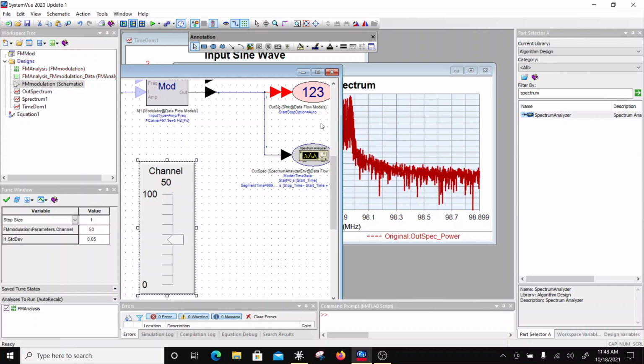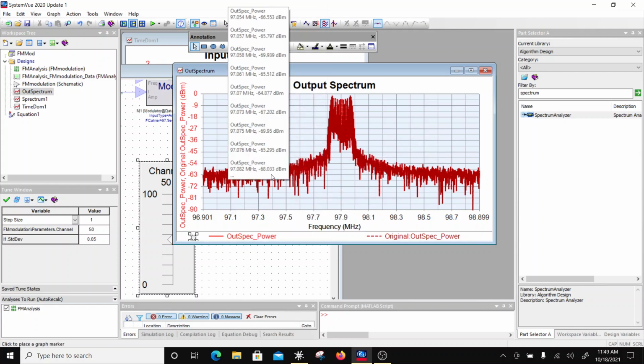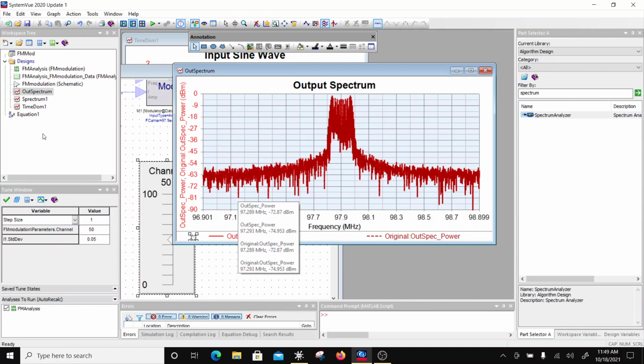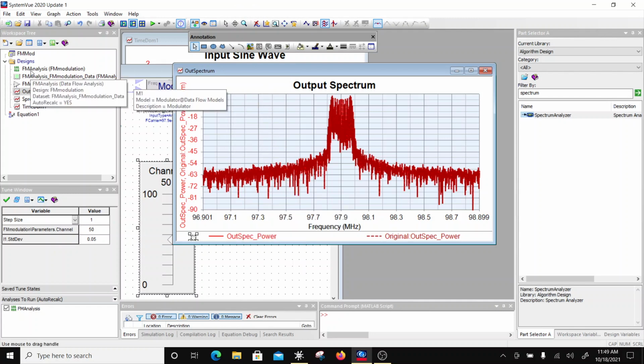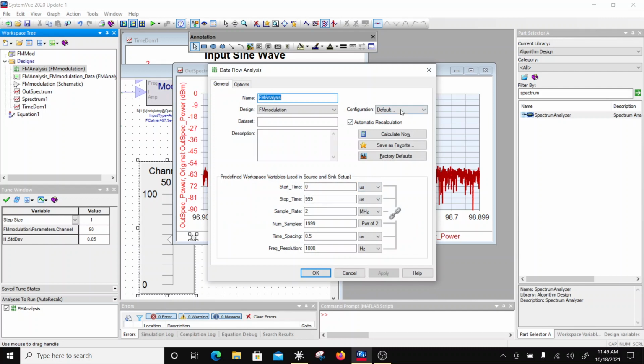So now you see the perfect match. Yeah, because noise is random, right? And every auto calculation is going to compute a different noise, right? So that's why unless you declare it as repeatable from calculation to calculation, the noise numbers are going to differ, right?